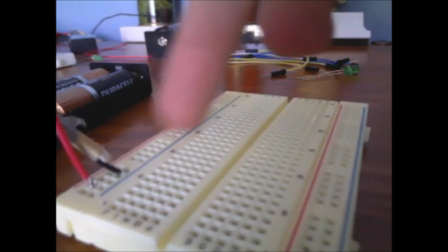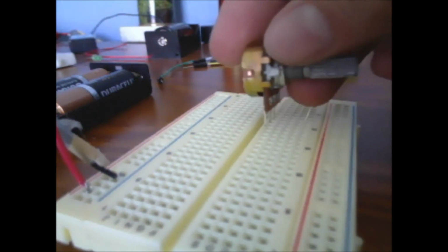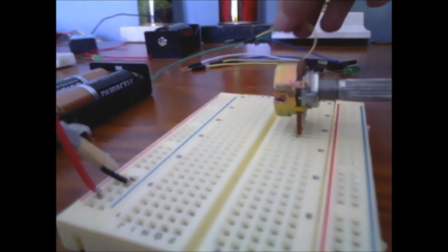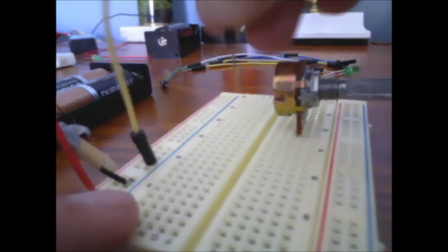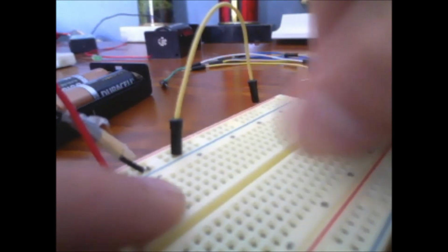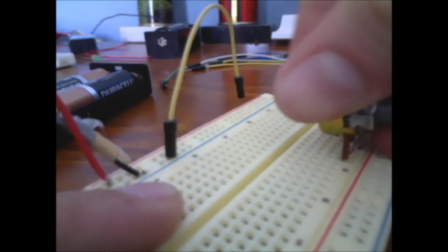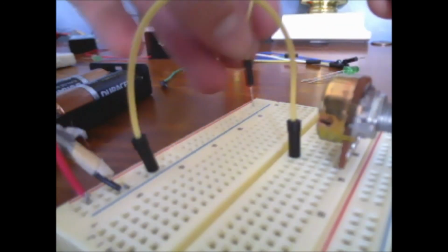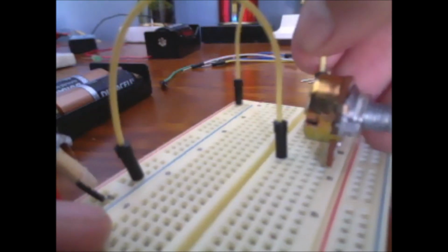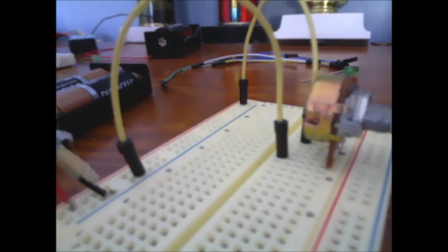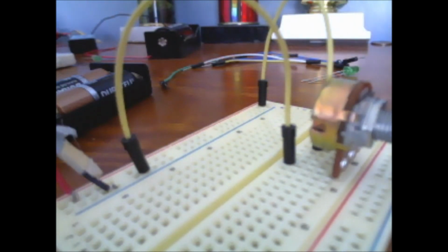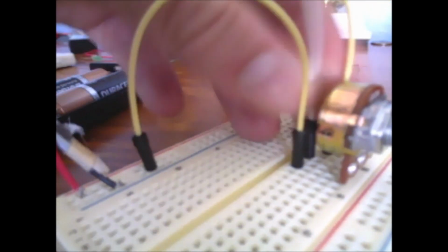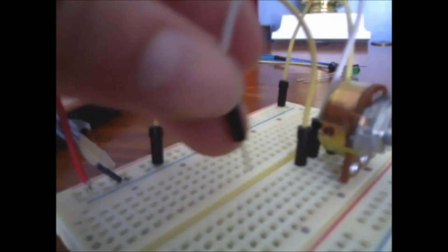So the first thing you're going to do is we have our power and ground rails on the breadboard right here. We're going to stick the potentiometer into 3 holes on the breadboard. And we're going to use our jumpers and connect the ground to one of the outer pins on the potentiometer. It actually doesn't matter which side you do, as long as it's one of the outer connectors. So we have our power and ground going in there, and the new voltage that comes based on a resistance is going to be coming out of the middle. So now we're going to connect the wire to the middle, because that has to be our new voltage that we're going to power the LED with. We're going to connect that to a new rail on the breadboard. I'm going to do one just right here.